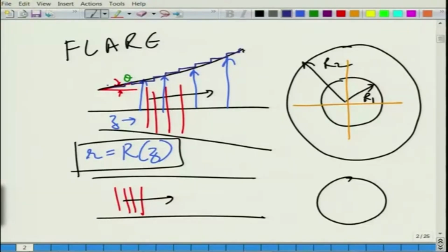So, there are very infinitesimal small discontinuities present along the section, and gradually from a small section we are able to get a much larger cross section. This is called a segmentation approach, we will talk about that in detail, but the idea of gradually varying area changes is to induce a continuous reflection of acoustic power rather than introducing a sudden impedance change.